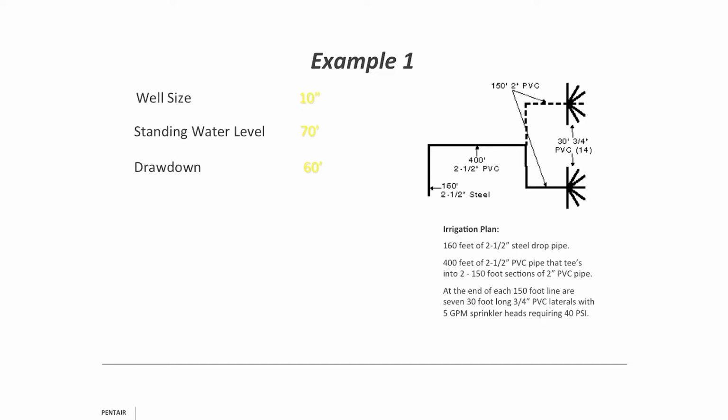But in irrigation zones, extra pressure they can adjust with sprinkler heads, or they can even put in a pressure reducer valve. But let me tell you something, if they're short pressure, they're going to have you for lunch. They're going to be angry, because their zones aren't meeting properly. So always round your numbers up when you're calculating, and always assume worst case scenarios.